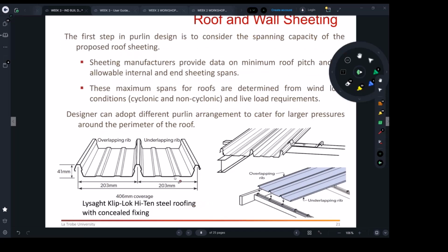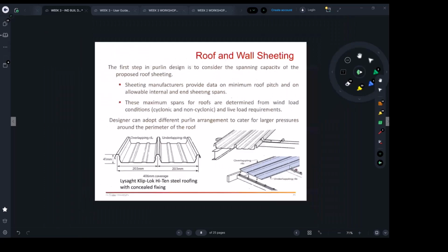I can tell you the engineering drawings don't specify these sheets. The architects do, but as a construction engineer, you always need to read what the wind load is, because the engineer on his front sheet will put what wind load is expected on the sheets on the building. Then you can see that wind rating and make sure those sheets can take such pressure from wind. Those are some of the checks you would do.